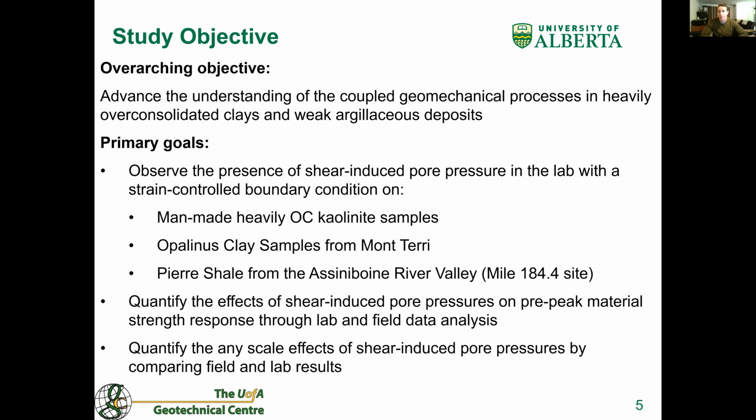To quantify the effects of shear-induced pore pressures on the pre-peak material strength response of this class of material, both through lab testing and field data analysis, and to quantify any scale effects that may be occurring when comparing the field and lab data.